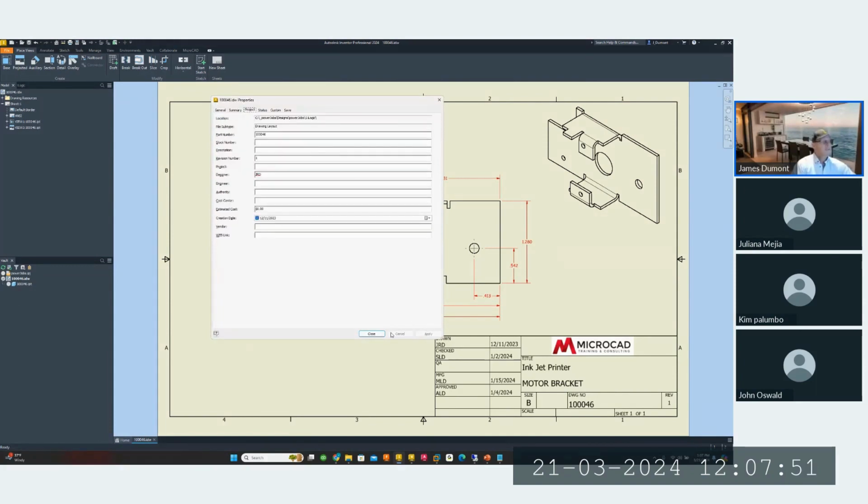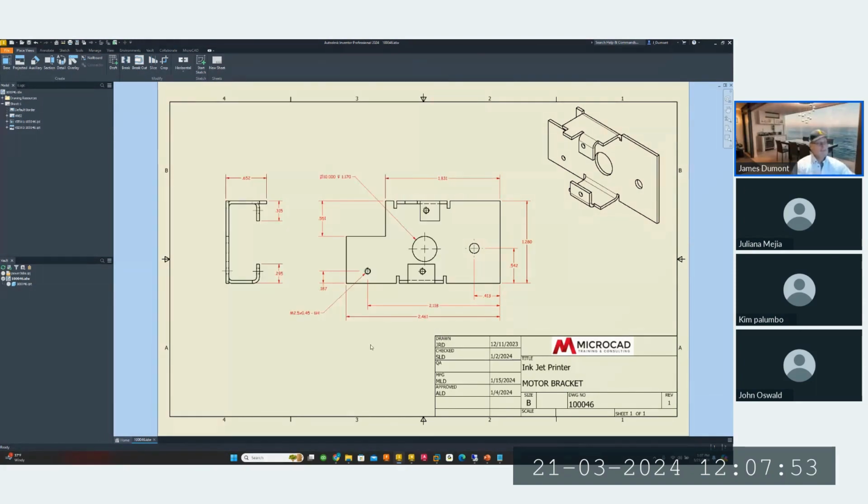So what I'd like to do, instead of doing any of the other manual steps, is use iLogic, and I like the external rules because if I introduce code today, it will be useful for files that you create from this point on and files that you've done in the past. If it's an internal rule that exists in the file, or if you did the template file, it would only be for new files. I like to make things a little bit more global.